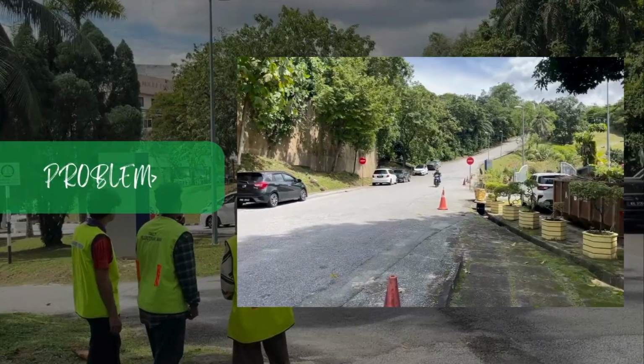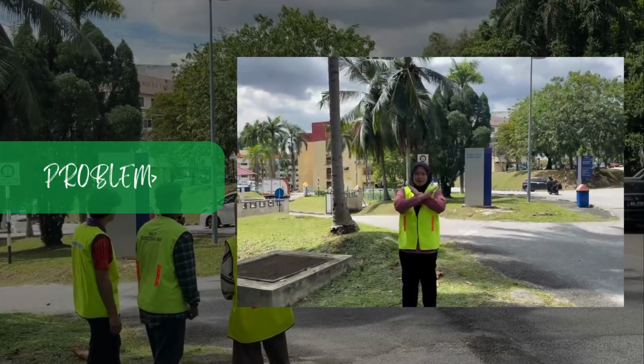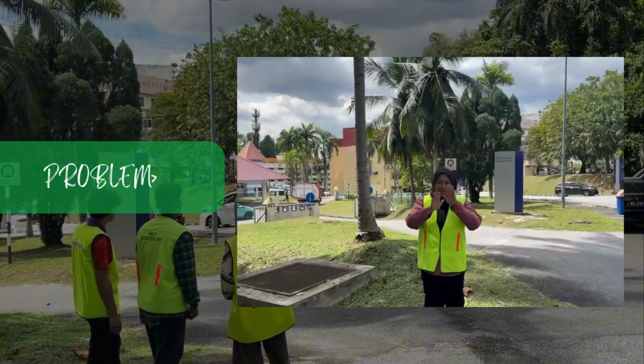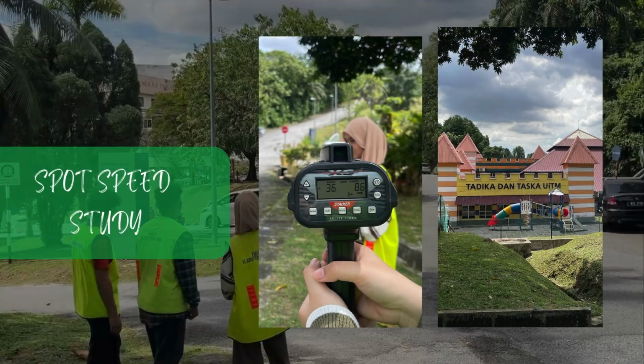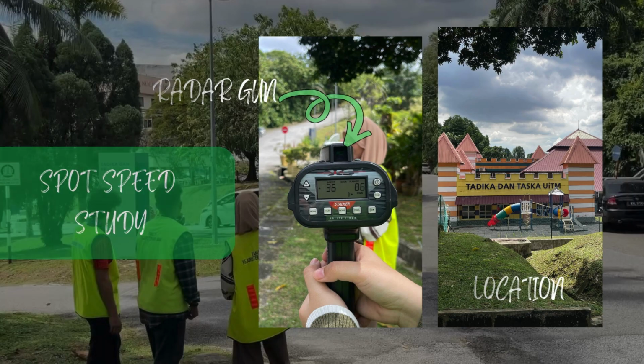This is because it is a downhill area where drivers tend to gain speed. The risk is higher because a kindergarten is located along the road, with children and parents frequently crossing during the peak hour. To support this finding, a spot speed study was carried out using a radar gun positioned in front of the kindergarten. Vehicle speeds were recorded at a fixed point for 1 hour to assess the actual driving speed.